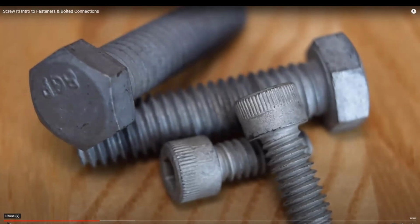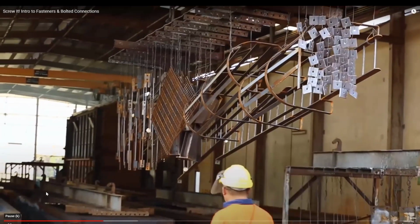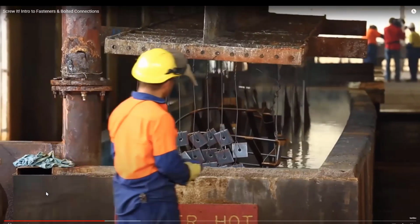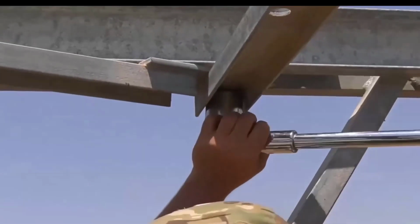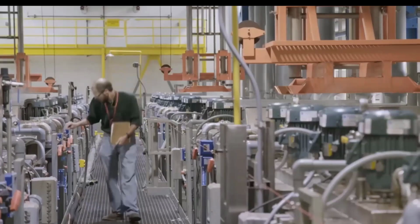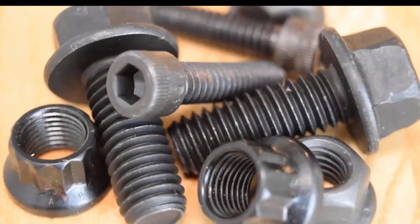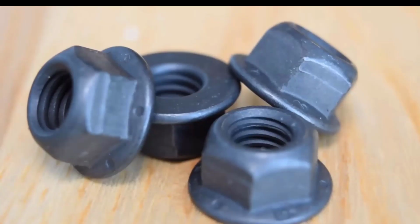This means that the raw bolt is dipped in a pot of molten zinc, which adheres to the base metal. This process is sometimes nicknamed hot dipped, and the resulting coating is much thicker than the electroplated zinc. Galvanized fasteners are typically acceptable for exterior installations. Aerospace fasteners are usually plated with cadmium. This is a very effective coating, but cadmium is an extraordinarily dangerous material, and these hazards are compelling manufacturers to find safer alternatives. Some fasteners, particularly socket-head cap screws, are coated with black oxide, and while it looks nice, this doesn't significantly improve the corrosion resistance over bare steel.